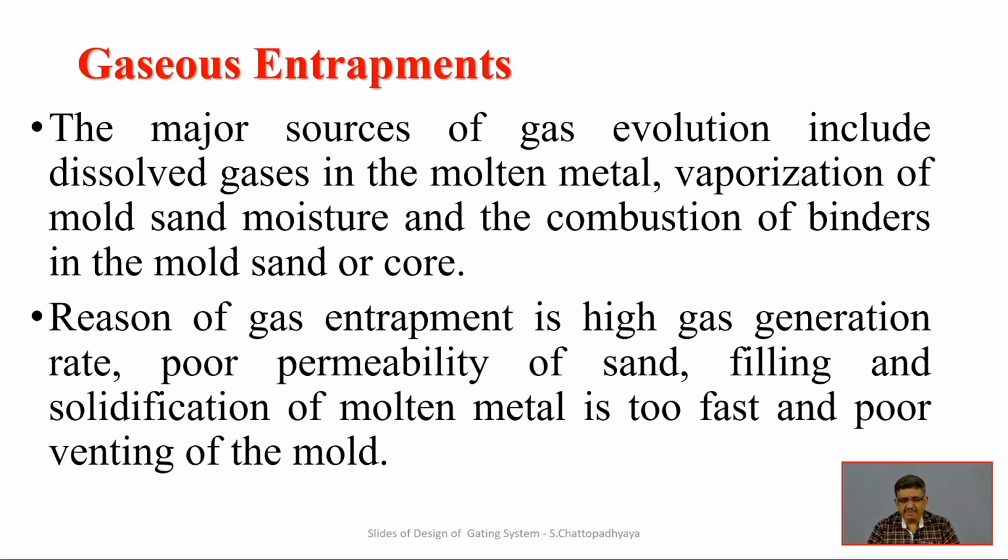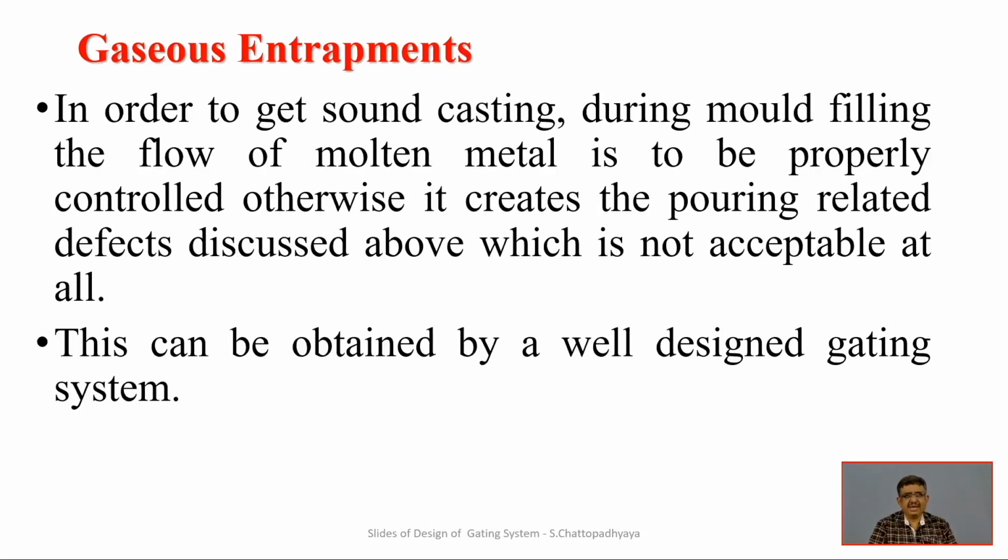That is why permeability of the sand is required, because highly permeable sand will allow those gases to escape before solidification, and that will result in the correctness of the casting. But poor permeability of sand, and filling and solidification of molten metal too fast, so fast that the gases cannot vent, and poor venting of the mold, all result in this kind of gaseous entrapment. This is the biggest problem. Sound casting cannot be obtained if gases are entrapped, and it has to be properly controlled, and this can be obtained by a well designed gating system.